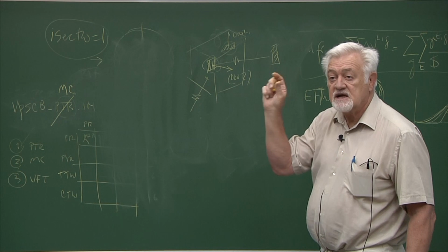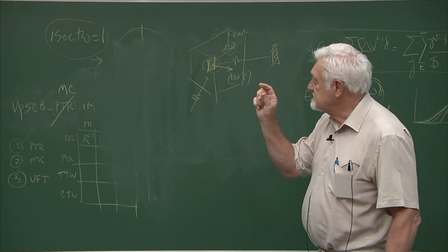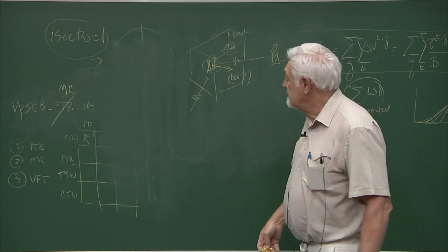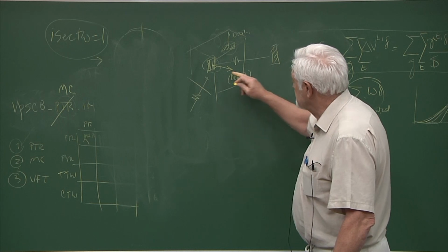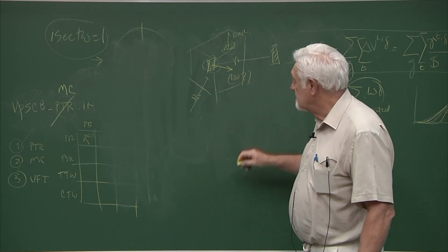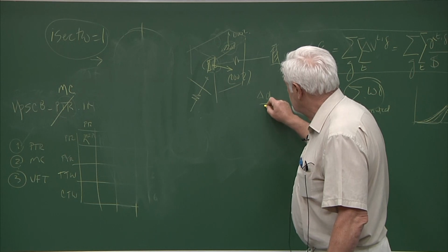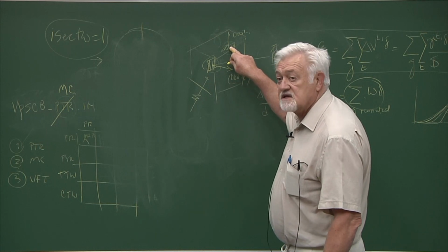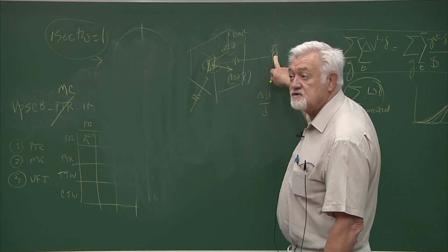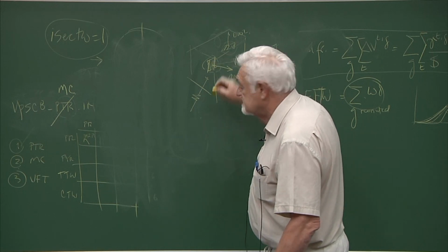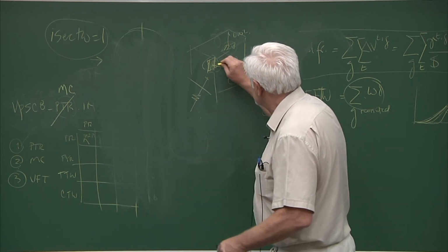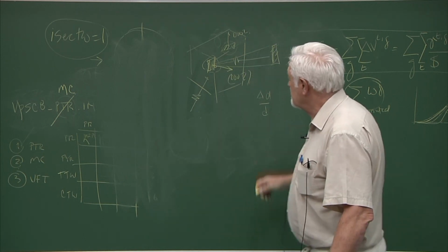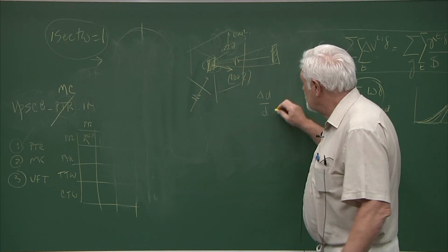There is an elastic strain that changes the separation between the crystallographic planes. And that is what you measure. That is a delta D over D, and of course this grain is not going to give you any diffraction into this detector. So only grains that are oriented like this or at small angle, because this detector spans an angle of about 15 degrees, only the grains that are within 15 degrees will give you diffraction.